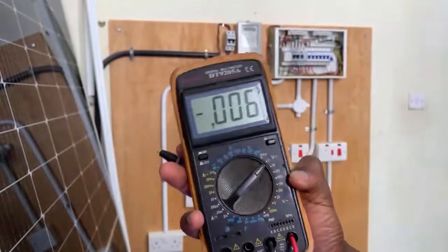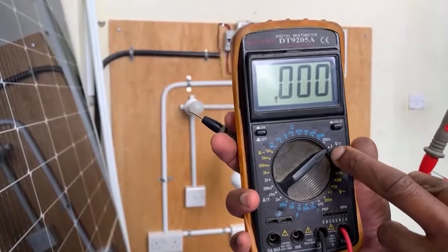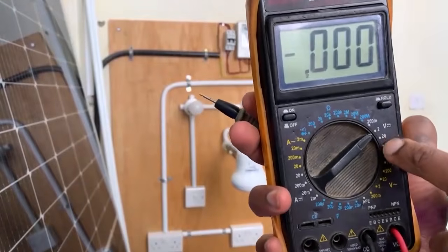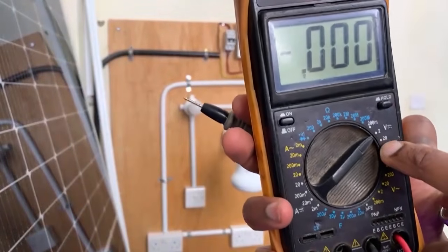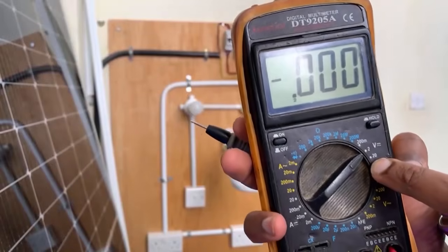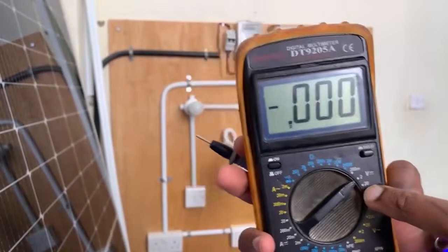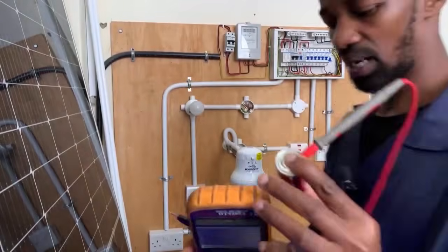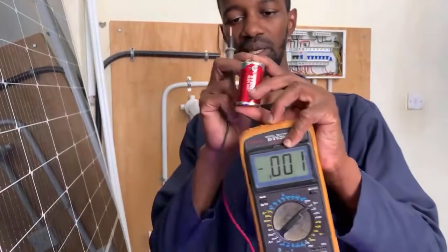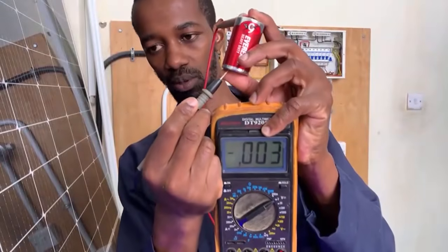Now, your volt, you see where you place before you record the readings. You see where I've placed it on 2, because I expect 1.5. If I place it at 20, that is too much. That is like taking a reading from a 12 volts battery or a 19.5 volts battery. When it comes to, like, let's say a laptop adapter, it gives a 19.5. I place it on the bottom.